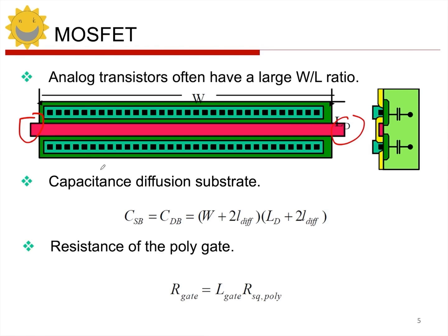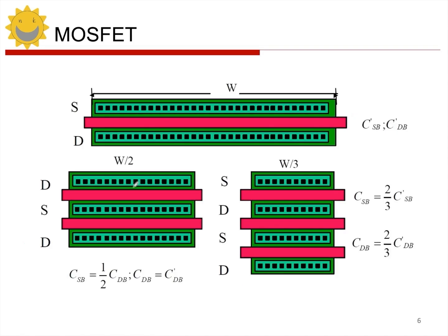So when we actually lay out the design to tackle the parasitic issues or to address the large-scale transistor, what do we usually use? We can use this finger structure to solve the problem. Now let's take a look at how to create this finger structure. For example, if I take this large, wide transistor and split it into fingers equal to 2, right?